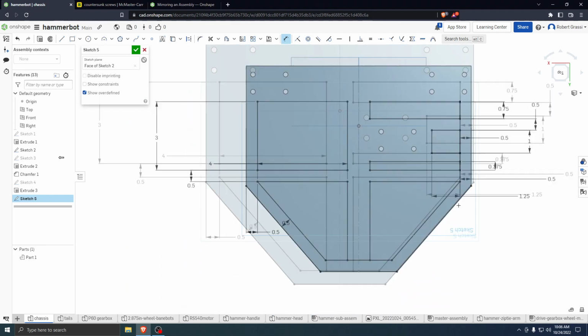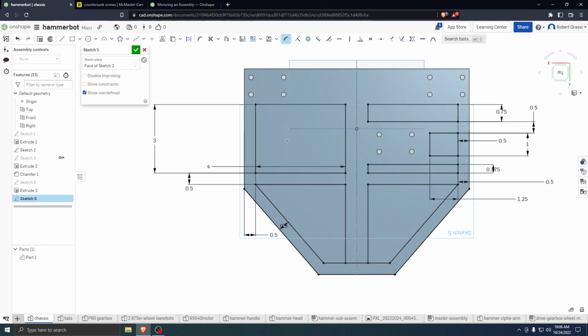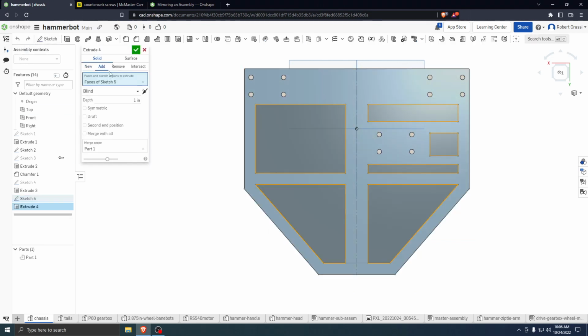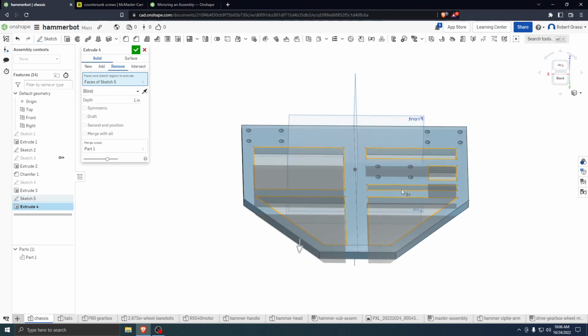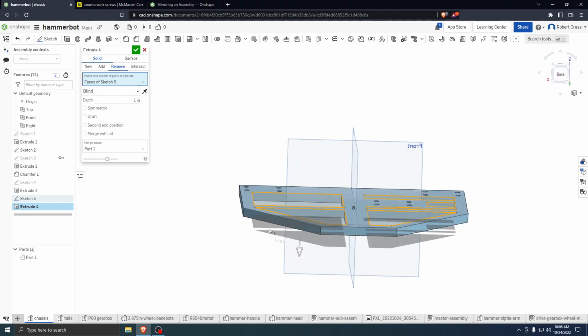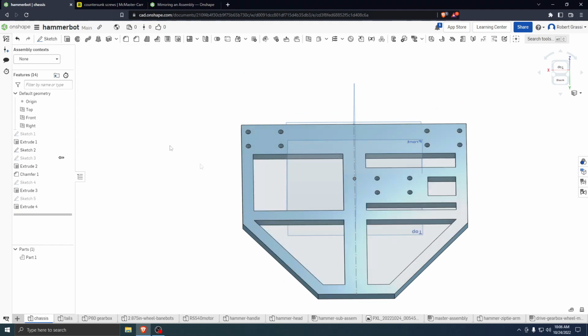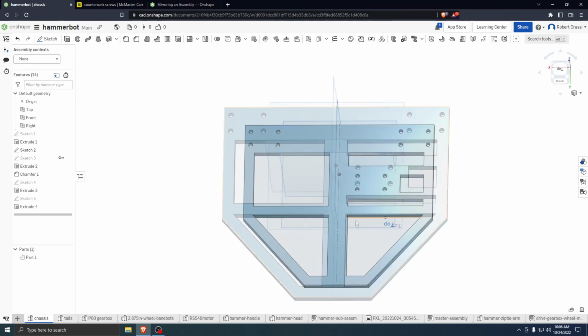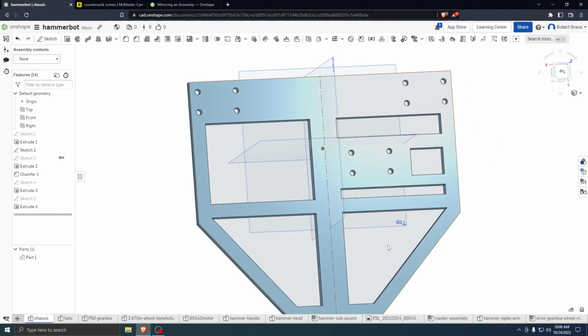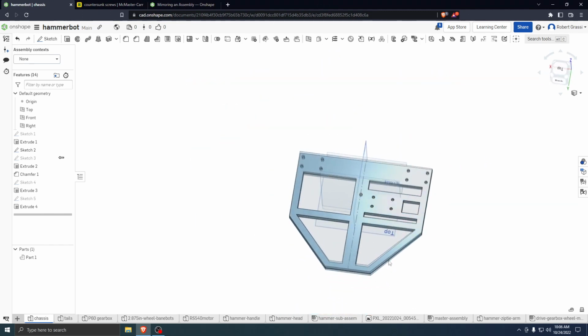Yeah. So basically, now what we want to do is select all of these regions. So 1, 2, 3, 4, 5, and 6, and extrude them, as a removing operation. Right, exactly. So we're removing them, and they're going down 1 inch, which is more than the thickness of the plate, which is fine. And just click OK. So now we have a plate with beams. Yep, looks pretty good.